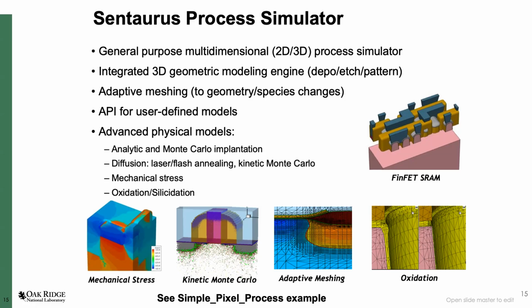So you will have smaller mesh elements where you have big variation, in that case in the doping profile or in the topology or at the interface, for example. You will try to have smaller elements so you have more precision in the simulation, and the tool helps you a lot doing that.